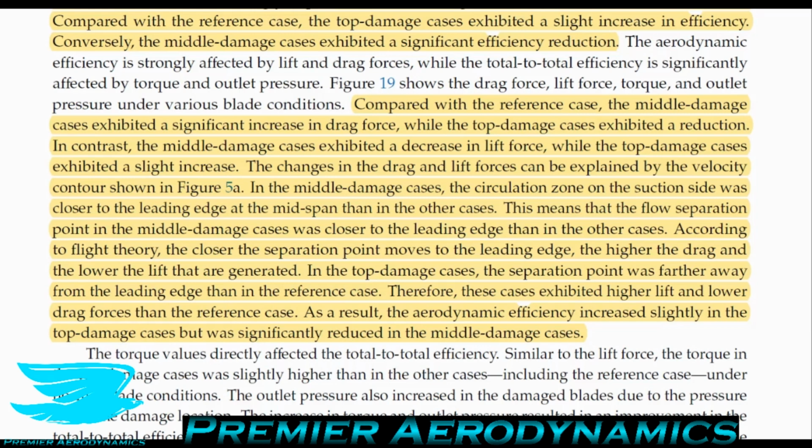Now, there are some times where this isn't the case, but generally speaking, this is the case. On the other hand, for the tip damage cases, the separation point was farther away from the leading edge than the reference case. So that means that more of the wing or more of the blade is producing lift and reducing drag. There's less separation flow over it. So that's why you're getting this beneficial result.